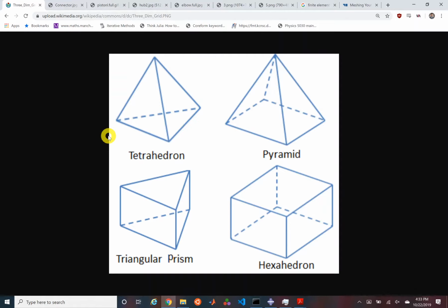There are significant mathematical properties that describe how these work. They tend to be robust. If you can construct a hexahedral mesh, the problems end up being smaller, typically fewer degrees of freedom. You can align these hexahedral meshes along surfaces and regions where the stresses are that you want to be able to capture accurately.